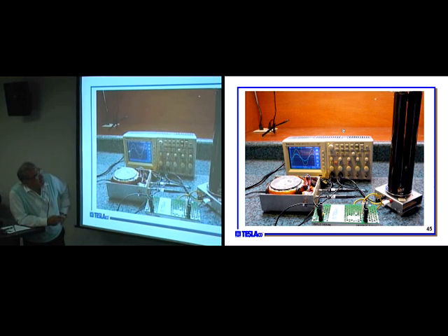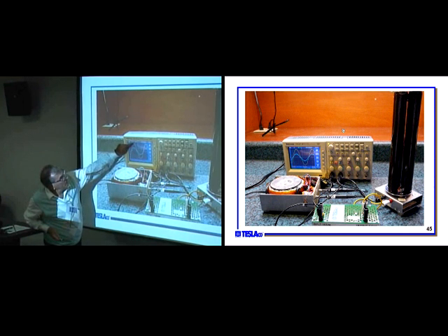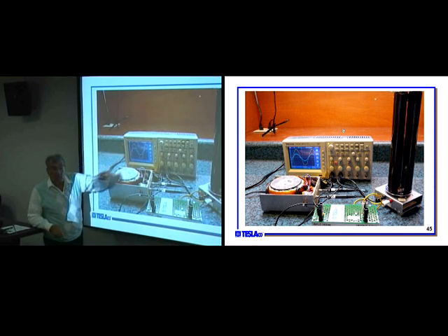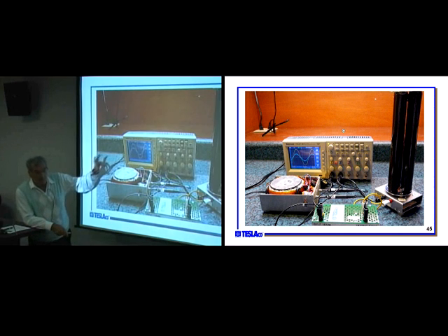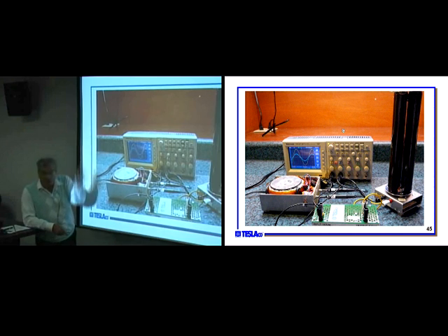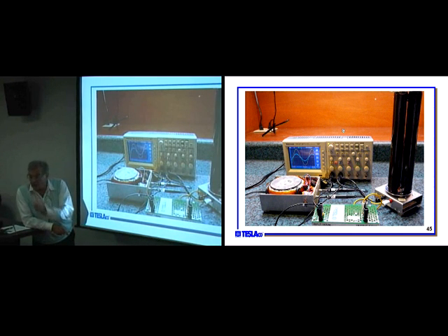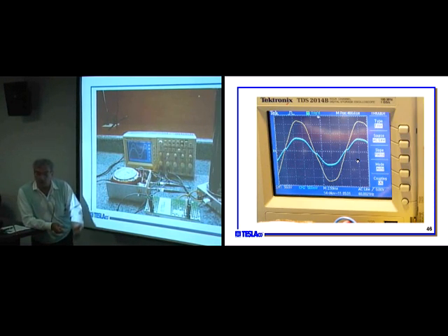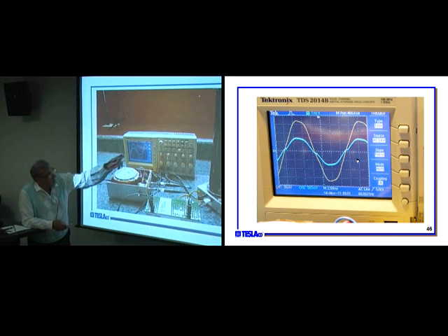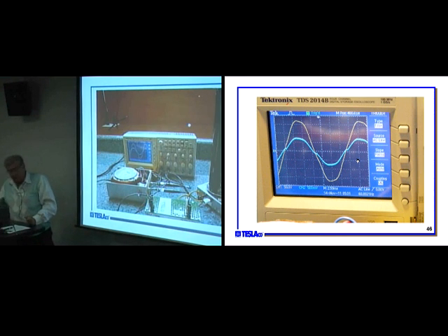So the point is, the AC line, you see, is not a sinusoidal voltage. I showed previously that sinusoidal voltage creates sinusoidal current, but the current in blue is directly proportional to the voltage. And why is this voltage distorted? Because in my building, like in any other building, everybody is rectifying the AC line with a simple diode bridge and taking the power at the peak of the voltage and loading it, making a bad power factor. And not only that, making bad harmonic distortion, which goes to every other user and contaminates their AC line and so on. So that's really the importance of power factor.